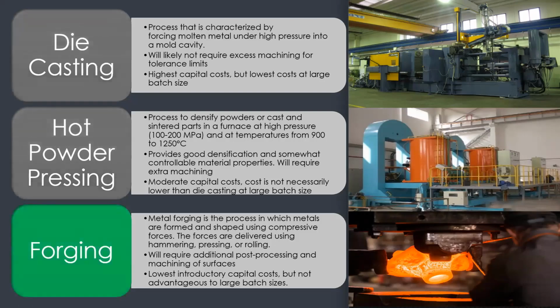However, ultimately we do choose forging, as our analysis tended to conclude that at a batch size of about 10,000 units, which correlates to 2,500 vehicles, which is moderate for this type of component, forging would actually be a somewhat cheaper option, even with regards to the post-processing and heat treatment methods that would be required for the part to be operable and usable.